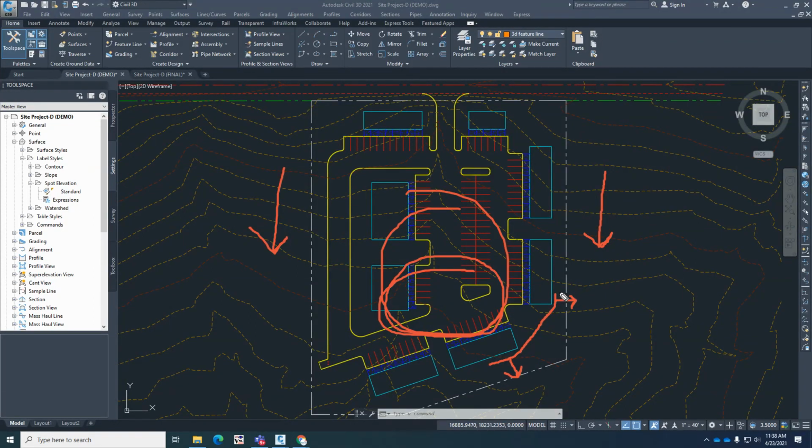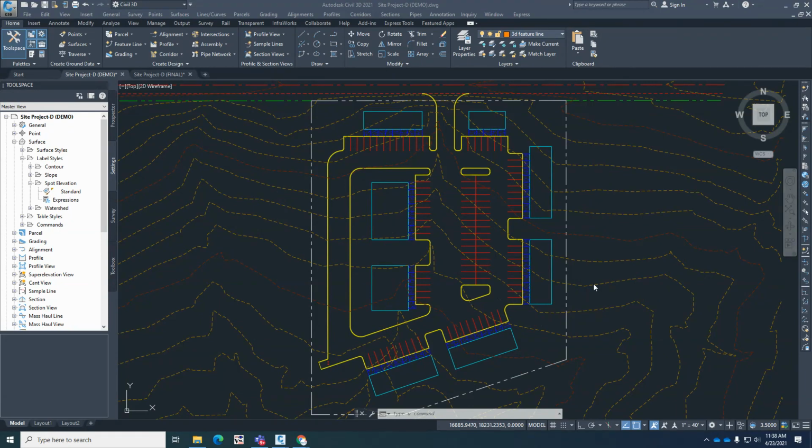Another thing too is those slopes, when you put the contours, more than likely might stretch out of the property line. Typically, we don't do that. You can't really do that in real life unless you have permission from the property owner adjacent to you, or maybe you own the two properties, or your clients do, however you want to consider that. So that's typically not done, but just to let you know that that's more than likely going to happen considering the 5% maximum grade on this project, okay?